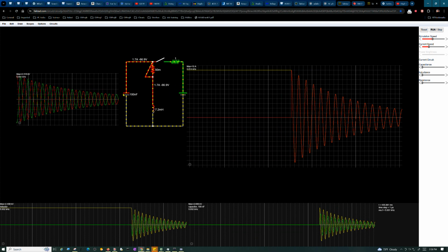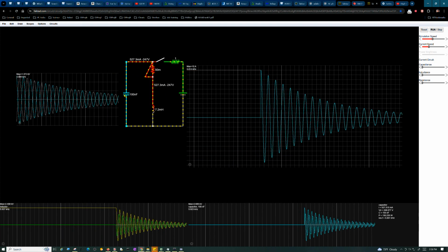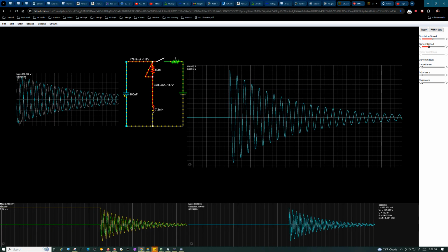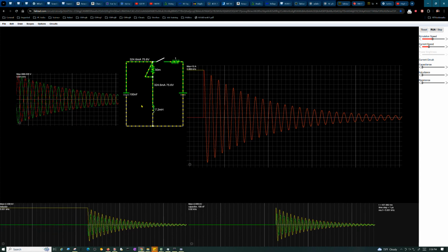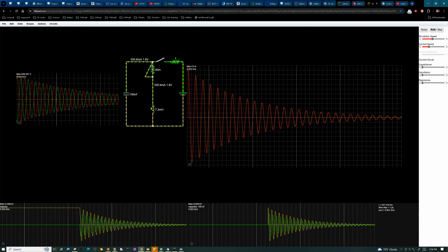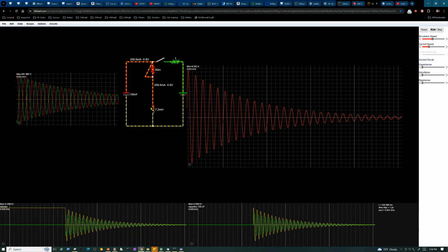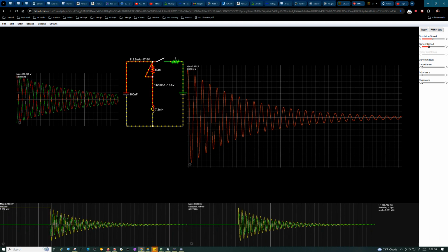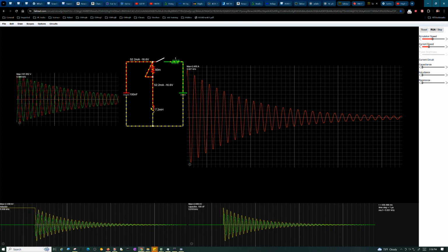But the problem is this capacitor can't handle half a joule at no low voltage. The only way a capacitor can store energy is to have it at a higher voltage. So that's what has to happen here, this interchange between the inductor and the capacitor. The inductor's got to fully run out of energy before it'll release its voltage. Then its voltage goes to 0 the moment it runs out of energy. Until then, it's going to generate whatever voltage it can, as long as it's still got energy stored in it, to get rid of it.